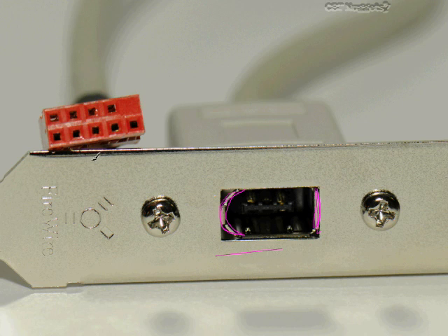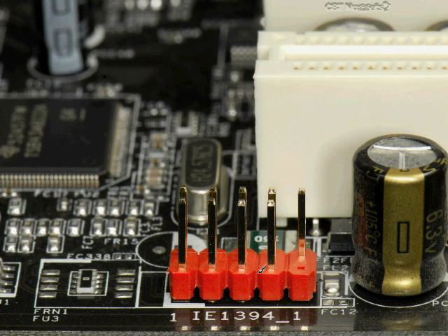And then notice here, this one's going to just go into a blank place on the case, and then this is our header connector right here. Notice that it's got an empty spot right there. That's for keying purposes, so that when you connect it to the motherboard, you can match the empty space on the block with an empty space on this header, and therefore properly orient that item. Now, one thing to keep in mind is that if you have to reach inside of a case to put that in, make sure that you know exactly where you're putting this, because you could potentially shift this accidentally to the right, and then the empty block would be over here, and one of the pin locations would be over here, but you would leave these two pins uncovered by the block, and everything would be shifted to the right a little bit.